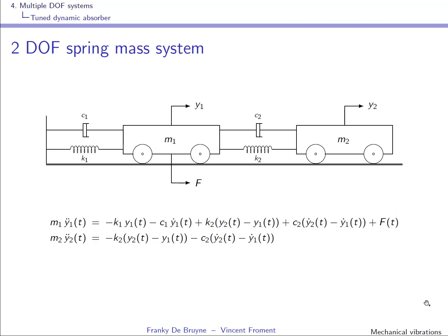Here I've chosen to do it differently, just the way we did it in the course of state space control. Remember that you could also write it down as x dot equals Ax plus Bu, and y is equal to Cx. So here we have used a first order differential equation.